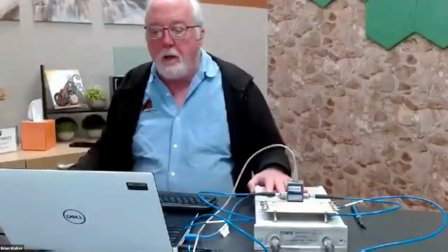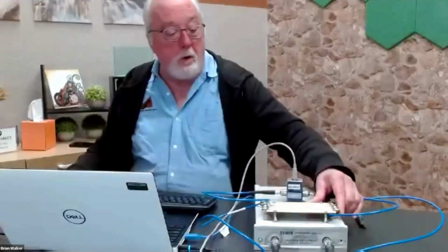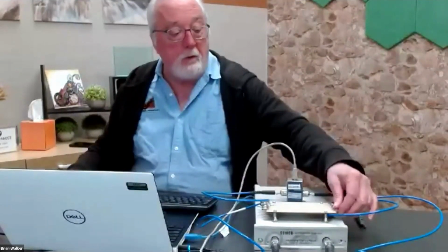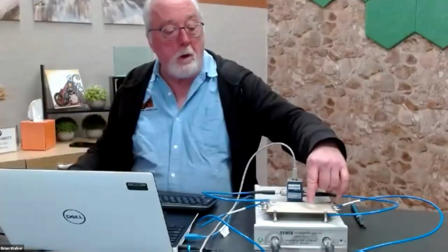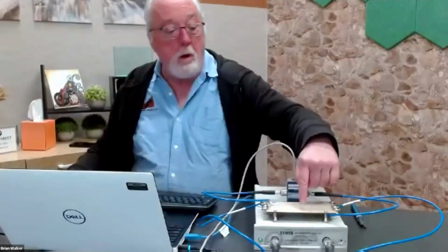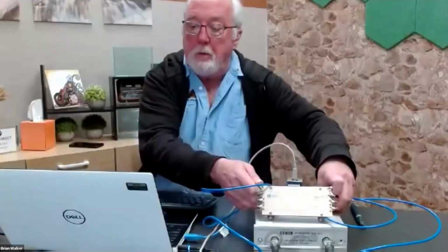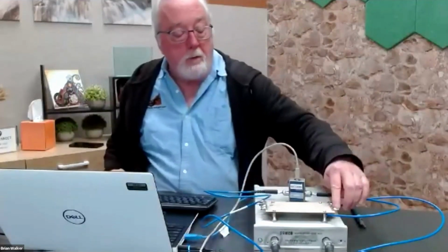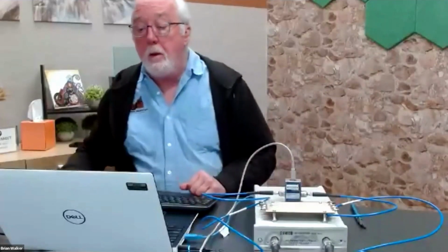So this is the S5180B VNA. And on top of it, I have an automatic calibration module. And this is my test board. It has a 100 ohm differential line on the top. And on the bottom, it has an interesting line, a microstrip line with an impairment. It's 2.5 inches of 50 ohm line, about 1 inch of 25 ohm line in the middle, and 2.5 inches of 50 ohm line. I don't think you can really see it in the camera, but take my word for it. So we'll measure first the 50 ohm line with a 25 ohm impairment and see that we were able to see that with the VNA.